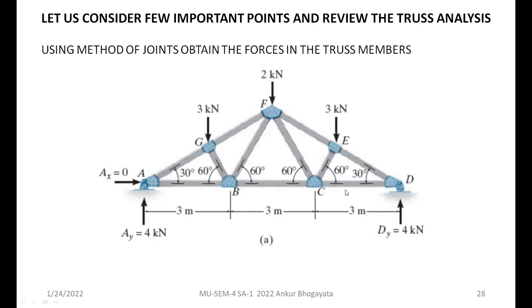3 meter is the bay distance between two members together, and even your work has been simplified, you can see that you have the symmetrical loading, so of course your reactions will be the same. So you just need to work out the values of the member forces.